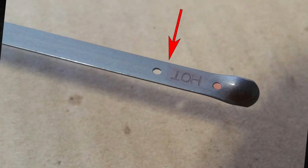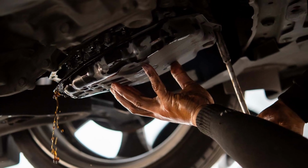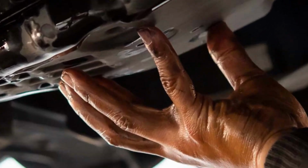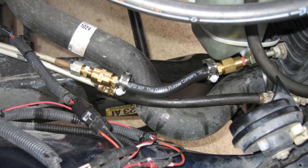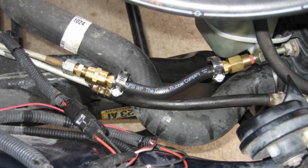Additionally, you ought to examine the fluid's quality. Change the fluid if it appears to be contaminated or outdated. To determine its status, compare it to a transmission fluid color chart. Check the transmission wiring harness for signs of rust, fraying, or other damage. Replace a connector or wire if you notice a problem.